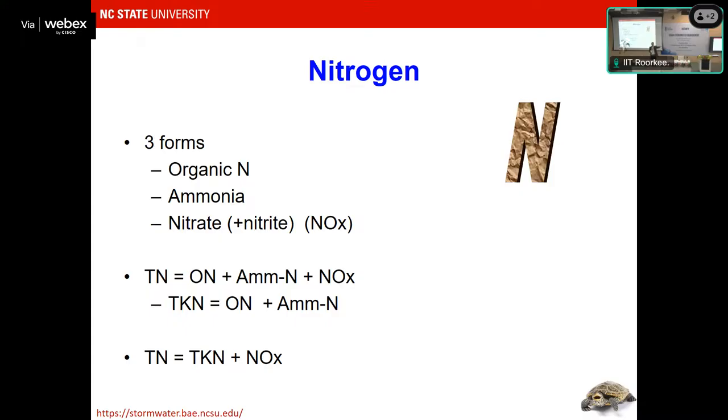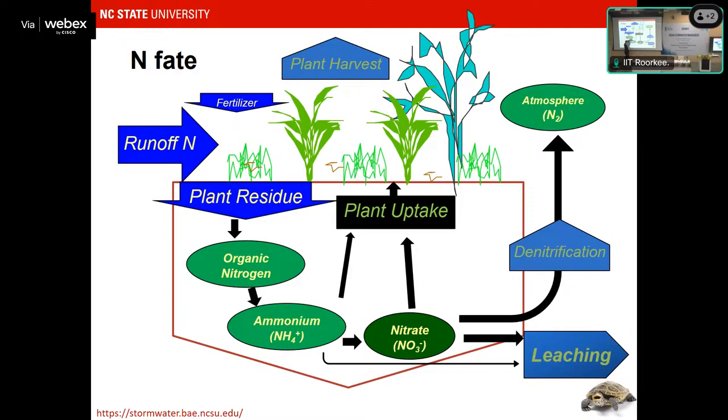Certain microbes convert the organic nitrogen into ammonia, and then that ammonia, in that same oxygenated environment, breaks down. Another set of microbes breaks it down into nitrite, nitrate being the stable state. And then you need to have the nitrate enter an anoxic environment where there's no oxygen, where denitrification to N2 gas takes place. All right?